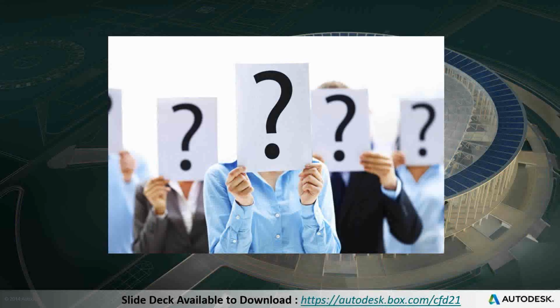Yeah. Right. Absolutely. 100% off topic, but when you're doing the electronics natural convection, same thing with radiation. Because it takes so much longer to solve, I'm going to run as few of those as I can. I'm going to do my baseline test, and then I'm going to benchmark everything without radiation, and then when I have the design I chose, I'm going to run radiation again just to make sure, but as few runs as I can with that. So if I don't have to run a model that's going to take a week, I'm not going to. That was 100% off topic. Well done, Todd. I suspect James might cover that section anyway.